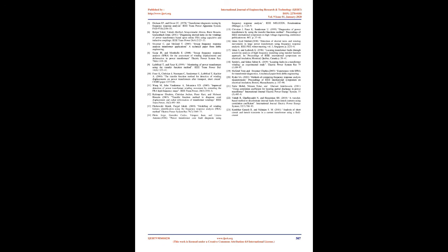Also, the low-frequency measurements proved to be very helpful for accurately monitoring the health condition of the transformer windings. Statistical indicators were used to support the interpretation of the SFRA results, and also quantifying the discriminative features associated with the interturn faults. The spectrum deviation and correlation coefficient proved to be effective tools to provide quantitative ways for diagnosing and, at the same time, to quantify the degree of the fault severity in the shorted turns.